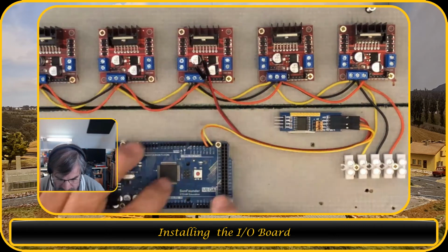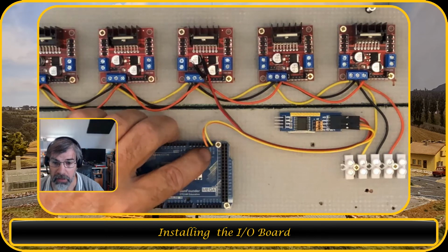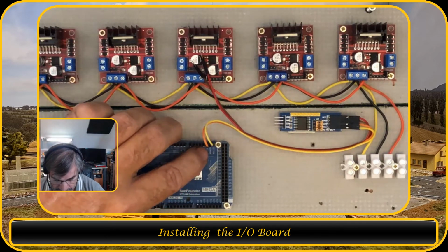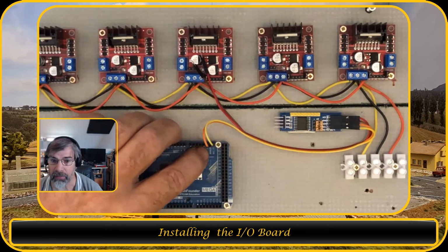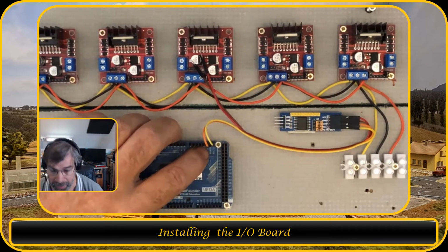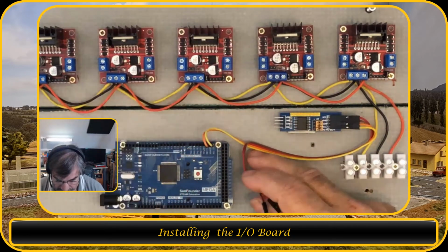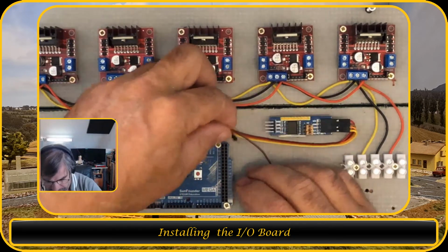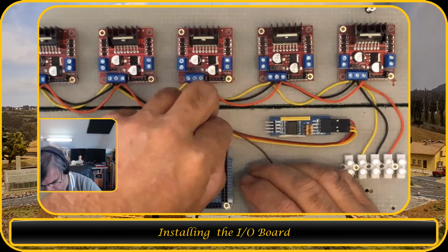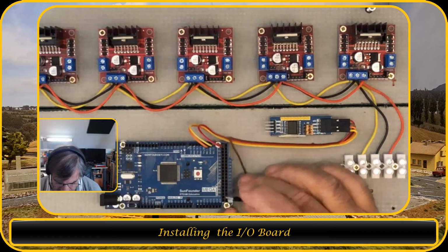So looking at this, pin number 21 is SCL on the Arduino Mega, and pin number 20 is SDA for the I2C bus on the Arduino Mega. And then we have the 5V and the ground. The 5V is this pin here on the Arduino, and the ground is at this end.